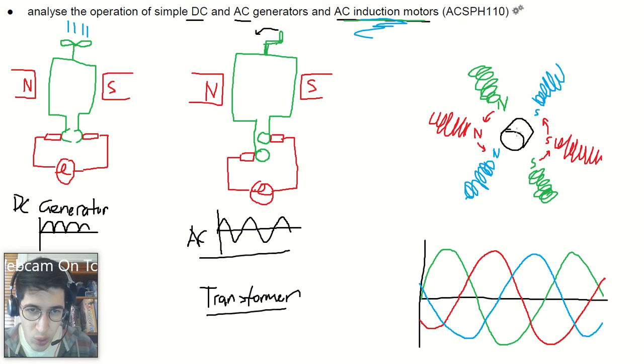This North Pole here, as it increases in strength, it increases the amount of magnetic field lines going into the surface of the cylinder here. That surface is going to respond. It's going to try and oppose the change in flux. It's going to produce its own flux against the north, creating its own eddy currents going around in this direction. So it's going to produce little eddy currents going around like this on the surface up there.